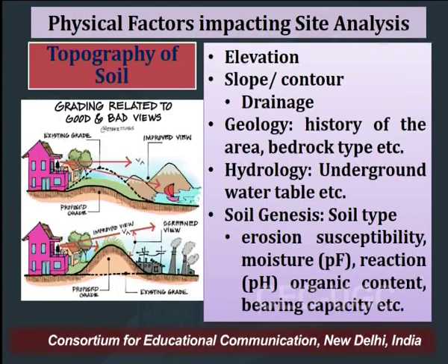The hydrology aspect pertains to the level of the underground water table, because on that the stability of the overall foundation also depends, because water makes the soil loose. So, where exactly the underground water table is present, it needs to be harnessed for the water requirement of the site also, plus it also impacts the overall stability of that site.